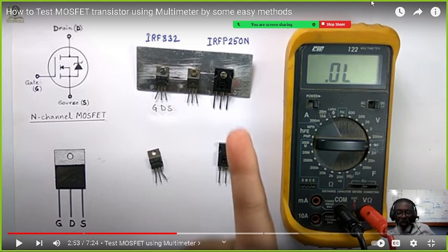But the test is for voltage, but the current is coming from the meter itself. Yes, from the meter itself, but a little bit. So I told him, in short, that in fact the circuit is not dead, because current still has to come through the meter.